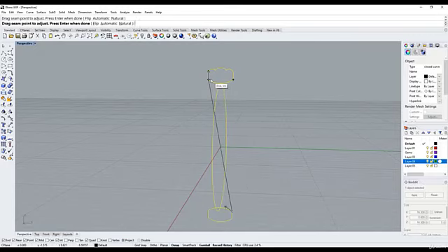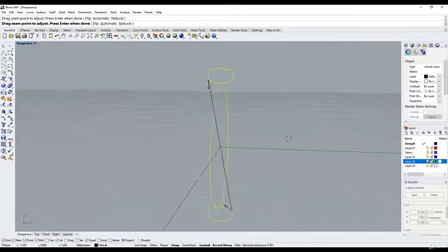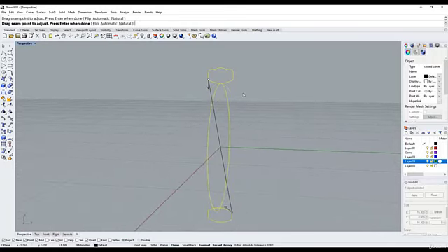But if you find that they're doing this sort of thing, then you're going to have a weird result when you initiate that sweep. So you can just come and click on one of these points, and in this case we want to align it here. Now this arrow is pointing away from the inside of the ring, whereas our bottom arrow here is pointing toward the center of the ring. So if we come and bring our cursor close to that arrow, you can see we're getting a second arrow pop out in the other direction. And once we see that arrow popped, we can just click and that's flipped the direction.